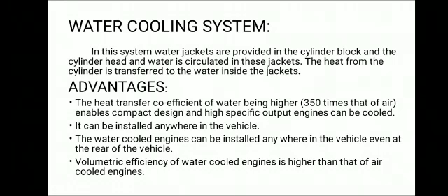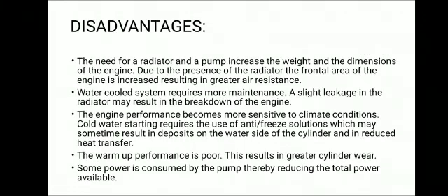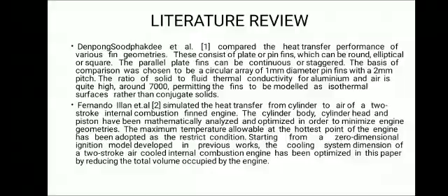Advantages: volumetric efficiency is higher. It can be easily installed anywhere in the vehicle. Disadvantages: the need for a radiator and pump increases the weight. It requires more maintenance. Warm-up performance is poor. Power is consumed by the pump.